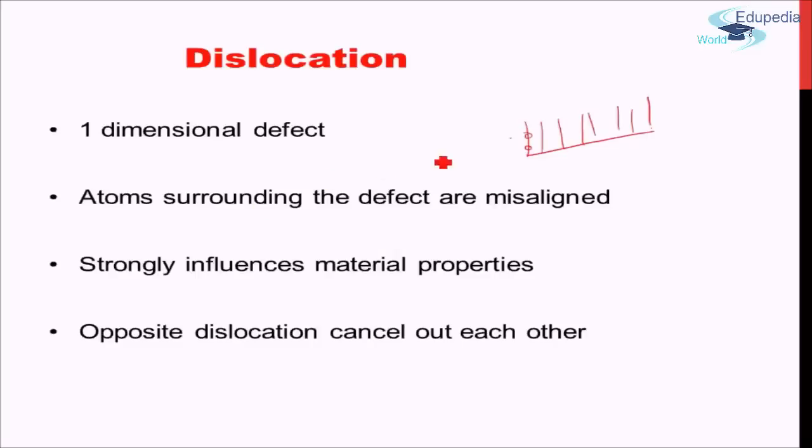And as I have drawn here, suppose we have a dislocation. This is normally, as we'll see, called a positive dislocation, denoted by this, if the extra plane of atoms is at top. And suppose we have another dislocation line here such that there is an extra half plane of atoms at the bottom, so that this dislocation will be a bottom one, right? The dislocations can move.